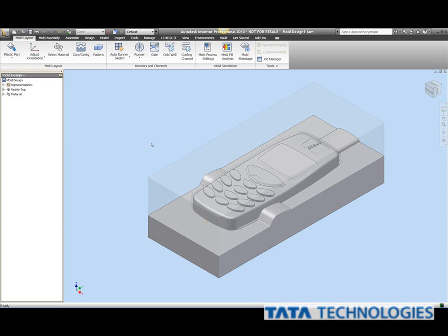We covered sizing the area of our workpiece, generating our core and cavity, creating our patching surfaces, also our runoff surfaces, and even placing the gate location. Well, now our next step is to think about sketching in our runner system.